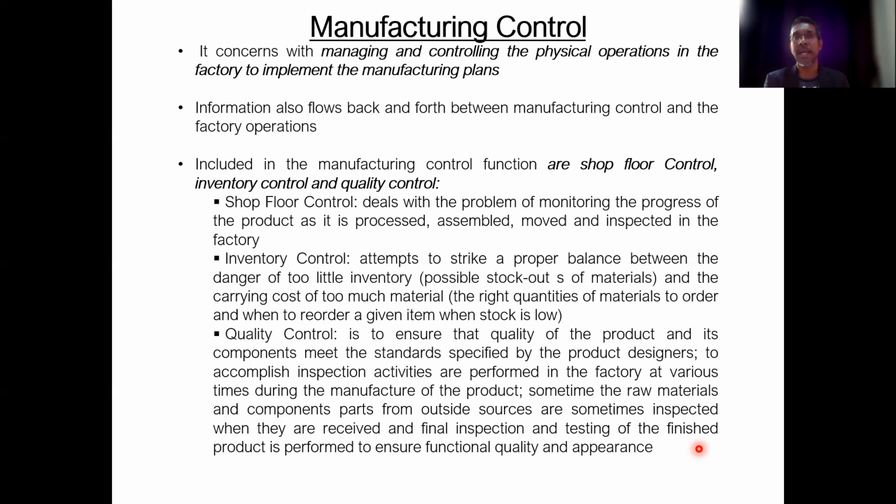We made alternators for cars. When we make them, they have an IC regulator. During assembly, for example, they have 4 bolts to tighten the IC regulator chip at the alternator. When the operator tightens the bolt, the tightening torque is always monitored by the operators. They need to tighten to the spec given by the drawing.